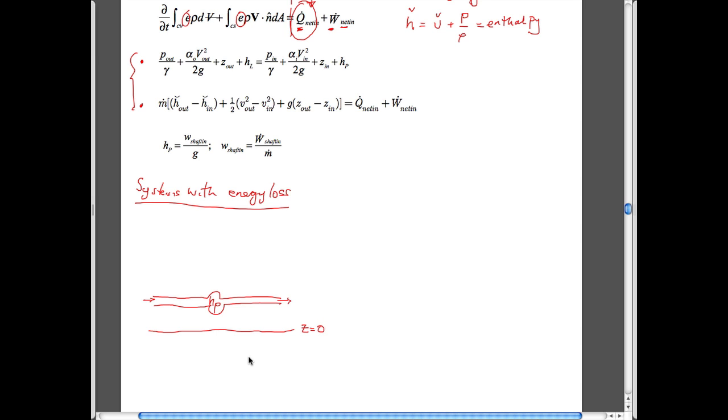And then let's talk about what we're going to be talking about in at least visual terms, in terms of the components of Bernoulli. We know that Bernoulli has three components that we've dealt with. One is an elevation head, one is a pressure head, and one is a velocity head. So what we could do is write, for each of these points upstream and downstream, and let's remember that we write these things upstream and downstream by convention. Didn't matter before, but it will matter now that we do it this way.